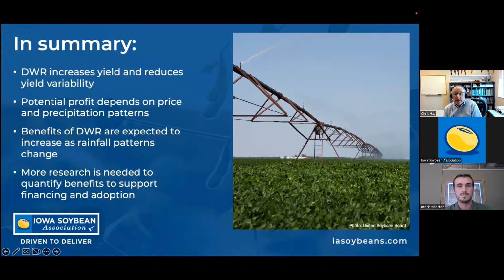It's going to depend a little bit on what we might look at as far as irrigation. So if we're looking at potential for sub-irrigation, we're going to want a site that's suitable for that practice. So we want one where we've got a pattern tiled system, we've got a fairly flat field, where we've got a good restrictive layer on the bottom of that field, which in most cases, if we've got drainage, that's the reason we've got drainage, is because of that restrictive layer.